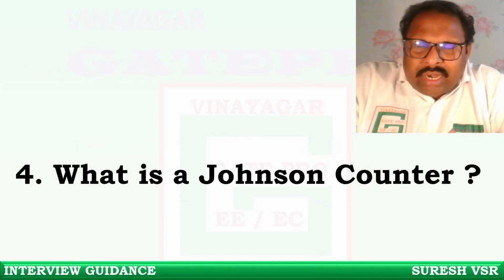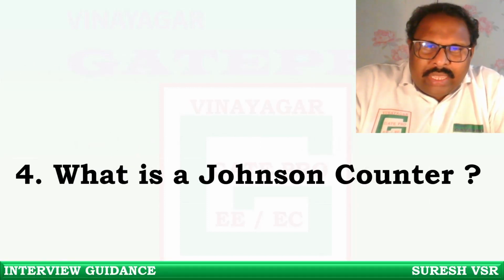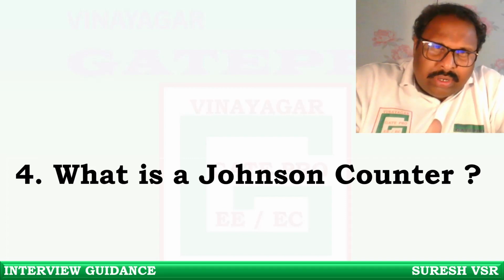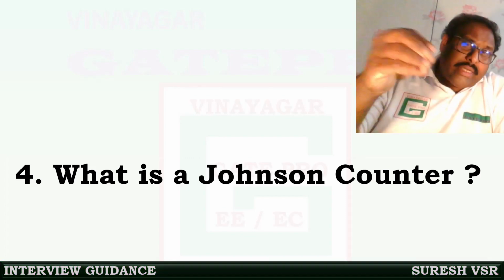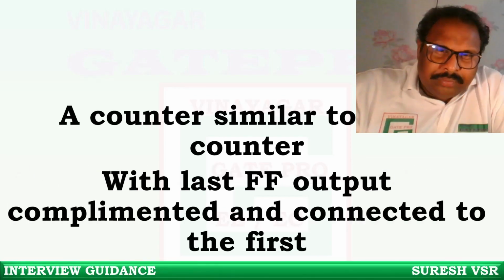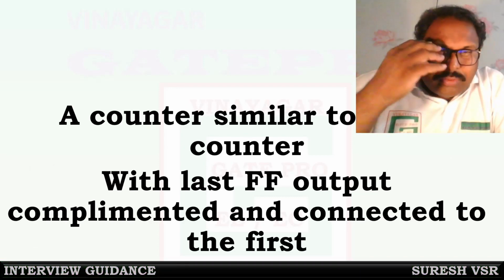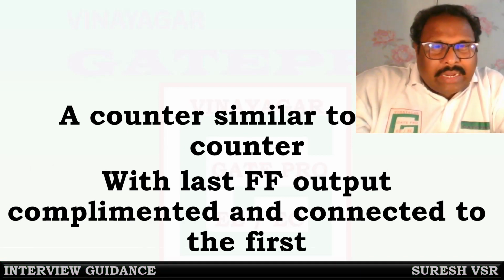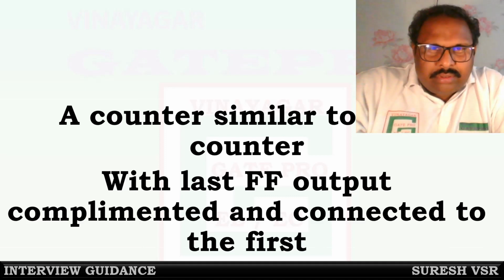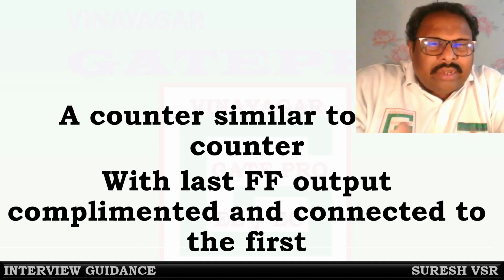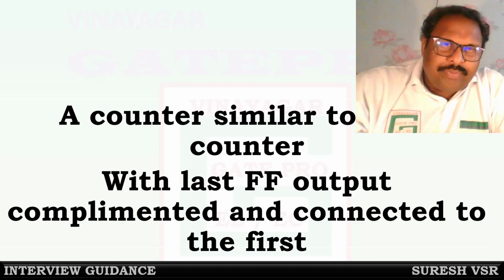Now what's a Johnson counter then? A Johnson counter is also a ring counter, except that the last flip-flop's output is complemented and then connected to the first. That's the difference between a ring counter and a Johnson counter.